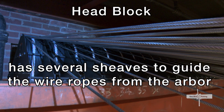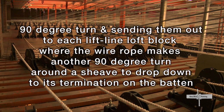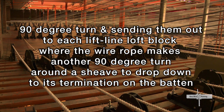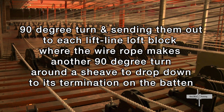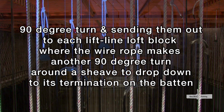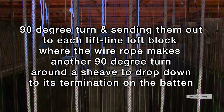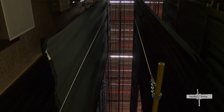The head block is above each arbor and has several sheaves to guide the ropes from the arbor, making a 90-degree turn and sending them out to each lift line block, or loft block, where the wire rope makes another 90-degree turn down to the sheave to drop to its termination on the batten. There are many more terms you'll encounter in the videos, but this gives you a good overview of the common systems and how they will work.